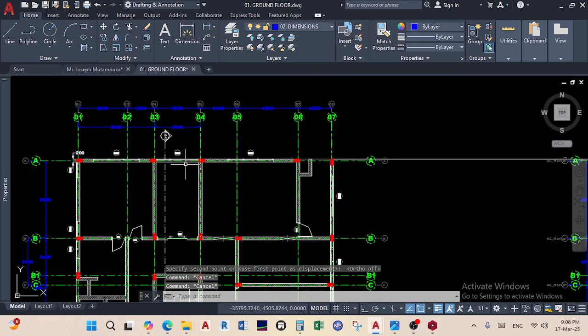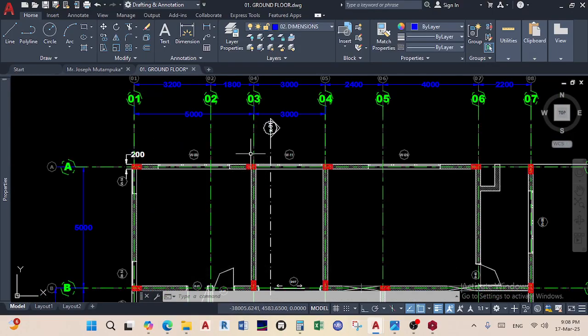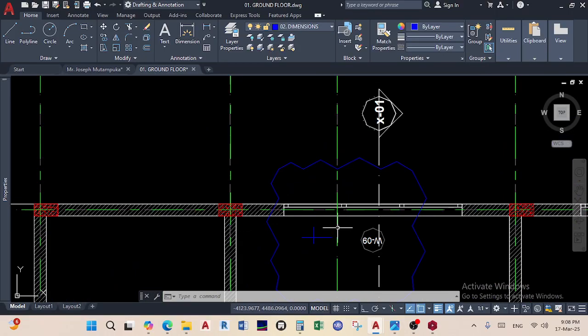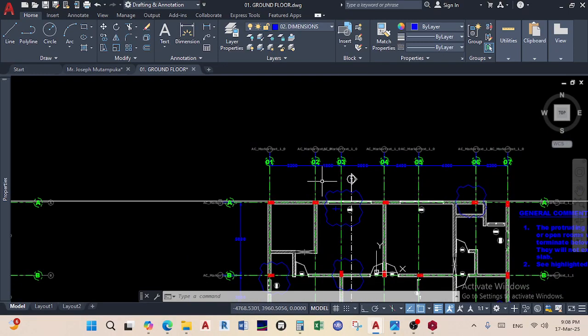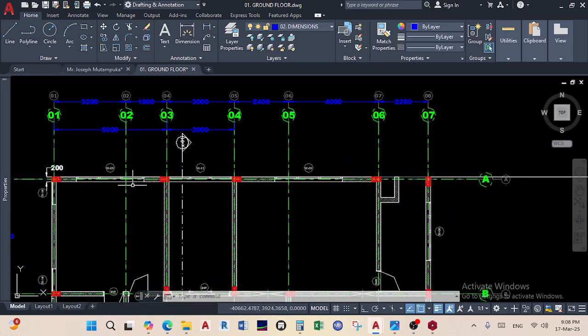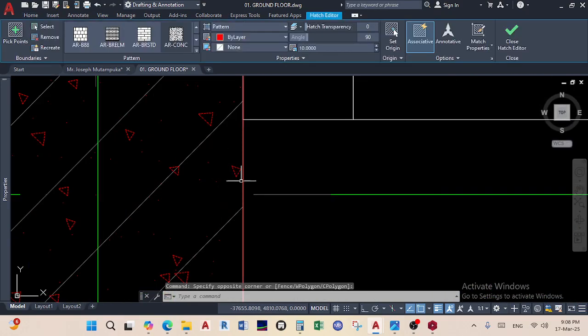So now here my 2 has to go here, my 3 has to go. My 3 on the ground floor sits okay. My 3 on my first floor cannot sit okay. It's in the window. Therefore now we change the spans. This will be like 480, this will be 320. So meaning now we've changed the entire design, column placement.